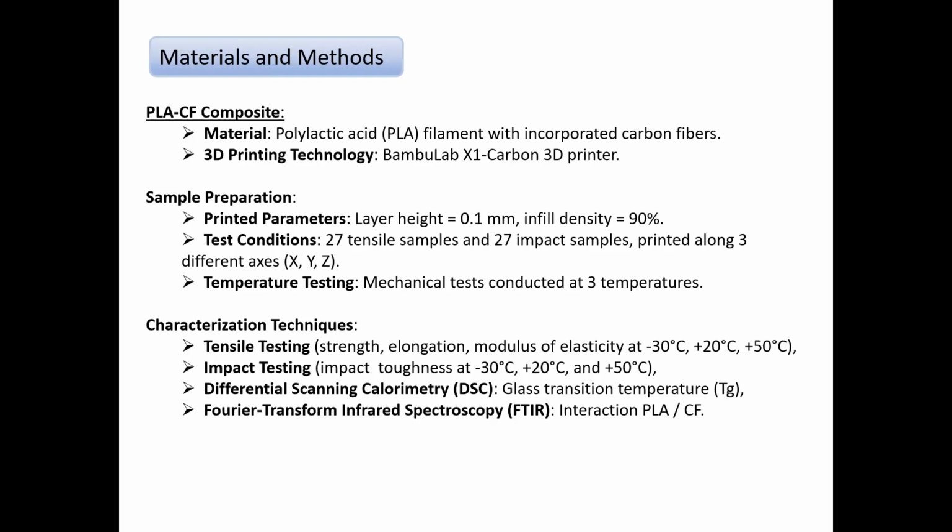What is the meaning of these two parameters? These two parameters are very important. It is well known in many literature sources that every additively manufactured sample is not a homogeneous material. It is an anisotropic material. It means that we have a lot of holes, and it is porosity. It is a great porosity. With this infill density of 90%, we talk about an approximately homogeneous material.